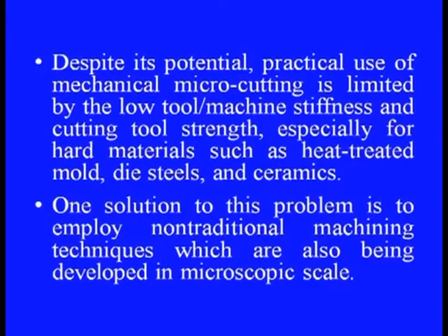Despite its potential, practical use of mechanical micro cutting is limited by the low tool or machine stiffness and cutting tool strength, especially for hard materials such as heat treated mold, die steels and ceramics. So, where is the solution then?